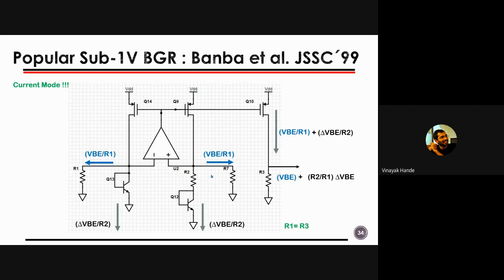He converted the voltage into the current and made it flow through another value of resistor, and he has scaled by a factor of lesser than 1, right? So that you can get the scaled bandgap based voltage, right? And as your reference voltage itself is operating at the scaled version of the actual bandgap based voltage reference, you have the luxury that you can operate at a lesser VDD, right?